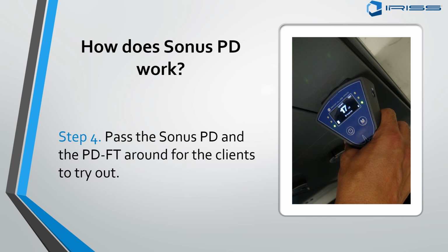All right, now go up to a piece of your equipment. Start using that TEV mode sensor in multiple areas on the equipment. Listen in if you're seeing anything. Look at the decibel value that you're getting. Look at the noise rejection level that you're getting, right? So you can just by that display tell whether or not you might have partial discharge taking place on a piece of equipment.